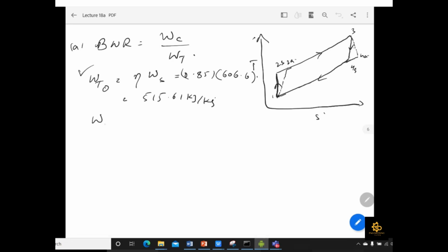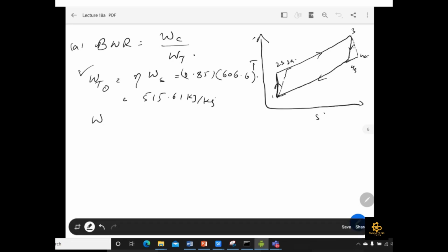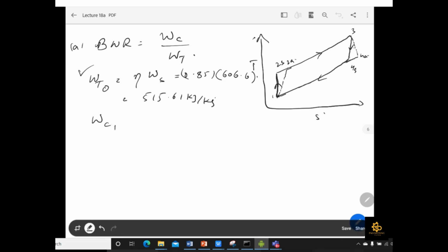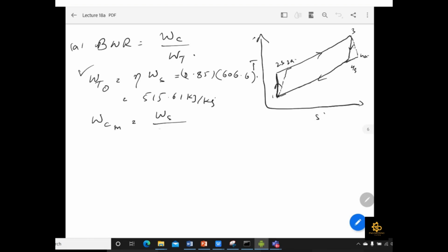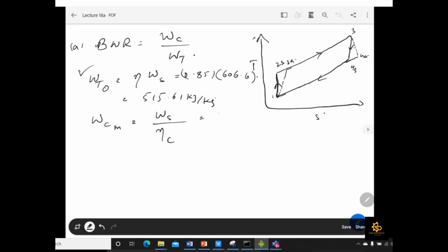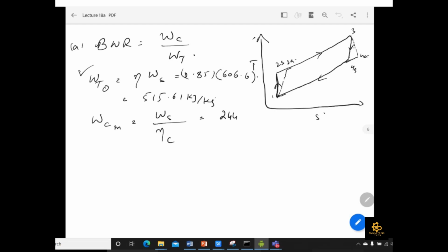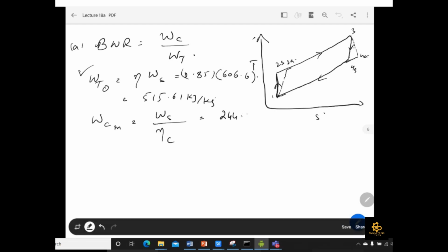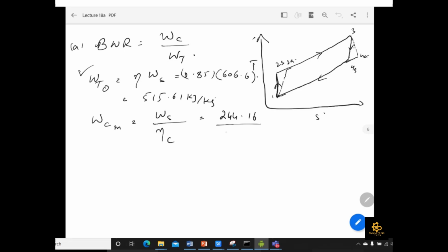Similarly, we have to apply the same thing for the compressor work. Because it is the in, the compressor in can be denoted as the isentropic work over the efficiency of your compressor. WS is taken from the previous example 9-5 because this is the isentropic work, and the isentropic efficiency is 0.8. From here we get the actual compressor work also, 305.2 kilojoule per kg.